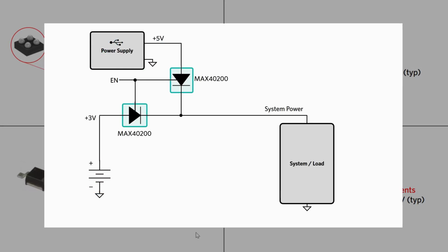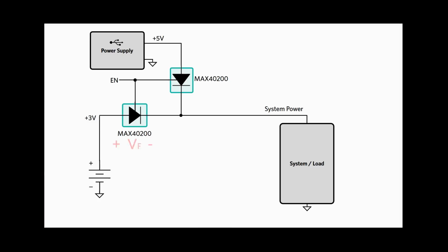There are also many products out there designed to be powered externally, but have an internal battery backup in case the external power supply fails. For products like this, where the battery is fully charged and perhaps not in use for years, having low reverse current when the battery is inactive is critical. Plus, when the battery becomes active in keeping the system alive when power is lost, a low forward voltage drop extends the battery backup runtime.